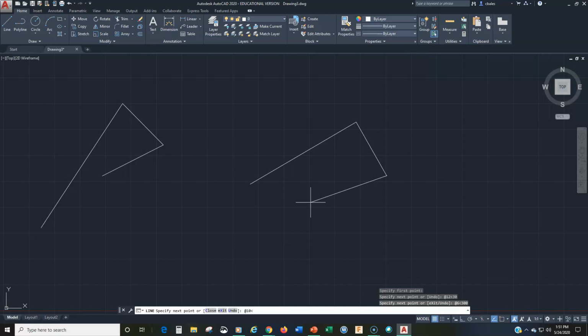Again, if we start from due east and we go, 90 is due north, and then we come around, 180 degrees is due west, it looks like it's about 20 degrees past due west, so that would be about 200 degrees. And I hit enter. Oh, pretty good. Okay. So those are the relative coordinate drawing methods, polar and Cartesian.